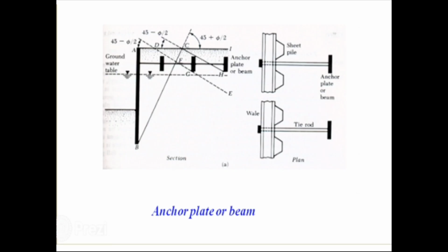Then, we have the anchor plate or beam. An anchor plate, floor plate, or wall washer is a large plate or washer connected to a tie rod or bolt. Anchor plates are used on exterior walls of masonry buildings for structural reinforcement. Being visible, many anchor plates are made in a style that is decorative.